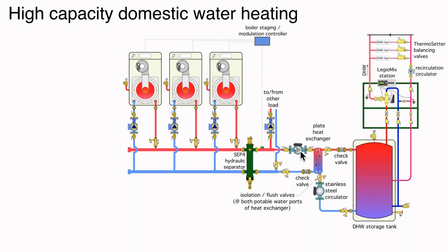This cannot be a little zone circulator. You can't move 800,000 BTUs per hour with an 80-watt zone circulator, all right? And some of you may be chuckling, but we've seen that as installed hardware. You've got a flow bottleneck. You're moving 800,000 BTUs per hour, you're probably dealing with 2-inch pipe and some pretty high flow rates, 40, 50 plus gallons per minute, way beyond what a little zone circulator can do.